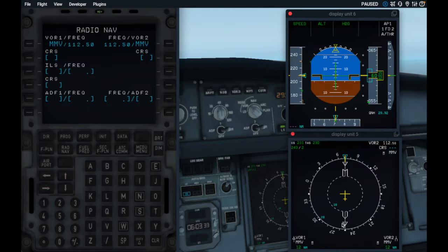If you look at the arrow mark, always remember, the arrow always points towards the VOR station, always, all right? So if this is the aircraft and this is the nose of the aircraft, you'll notice that the arrow is pointed behind the aircraft. That effectively means the VOR is behind you, right? So, perfect. Now, which way are we heading?